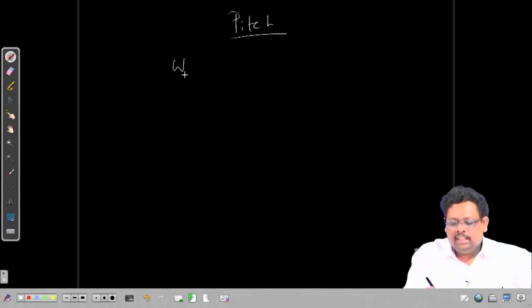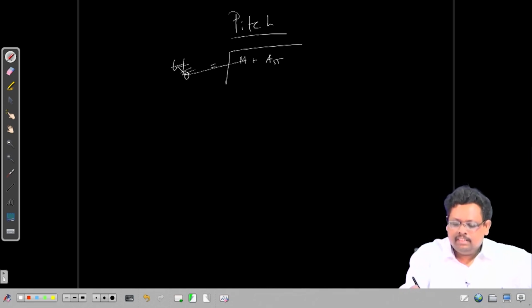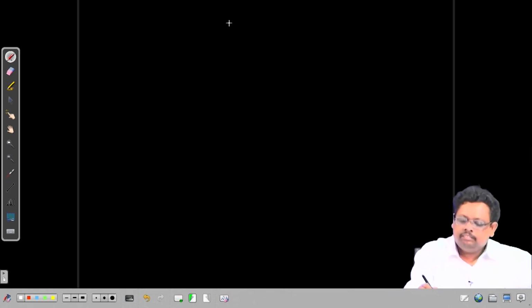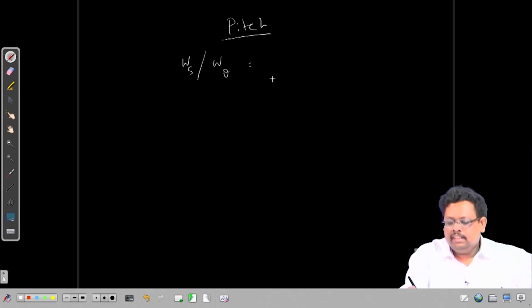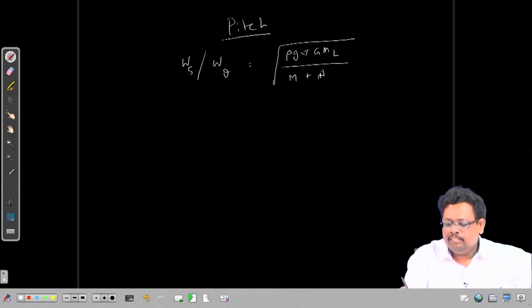You can call this omega theta, or omega 5, and this equals the square root of rho g V into GM L divided by m plus A 55.